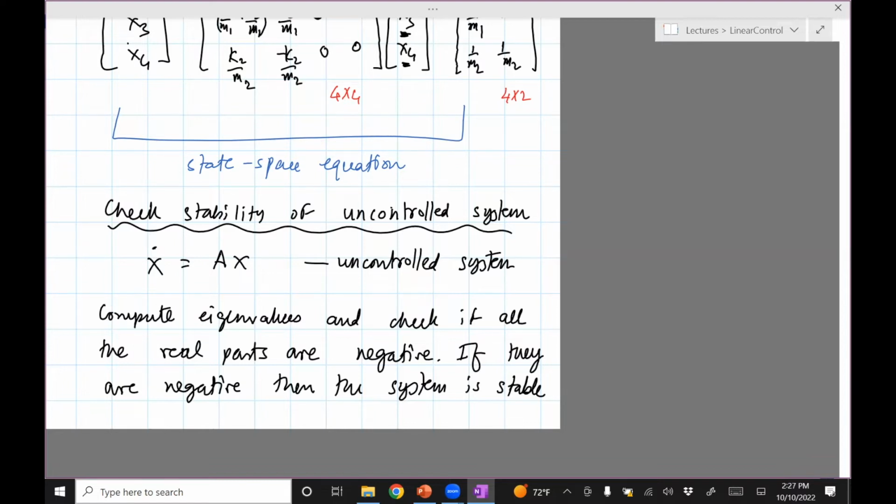Now, it sometimes does happen that the eigenvalues are not negative, not positive, but imaginary. If you've taken a control class, they lie on the y-axis. In that case, the system is said to be neutrally stable, so it will not remove or add energy. A spring mass system is neutrally stable because if you perturb it, it will just keep wobbling around. The oscillation will not damp out or grow.